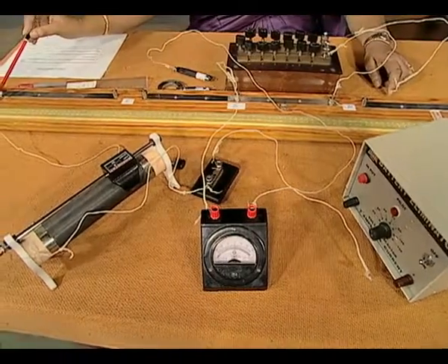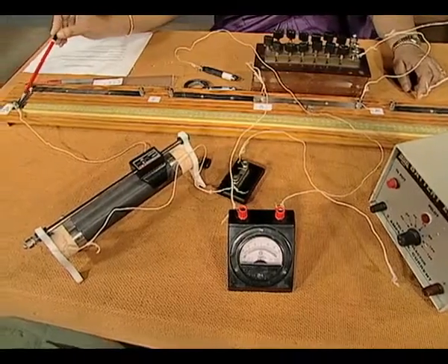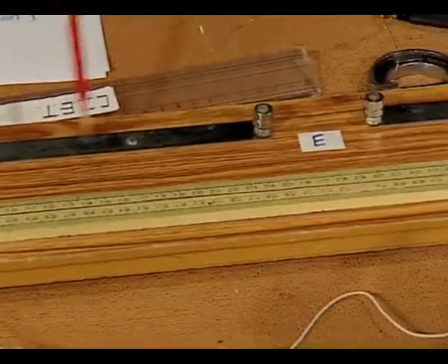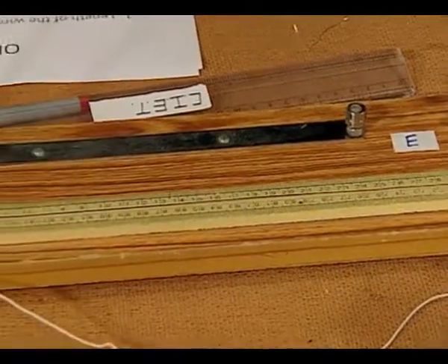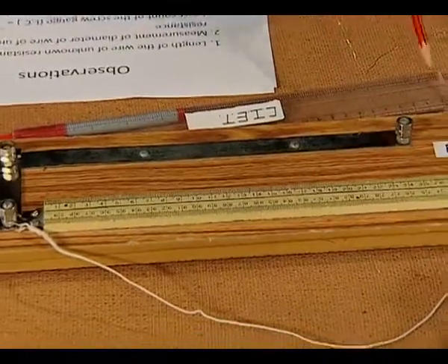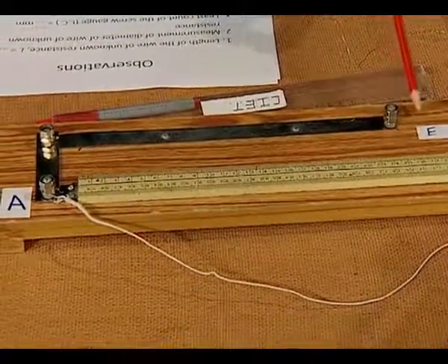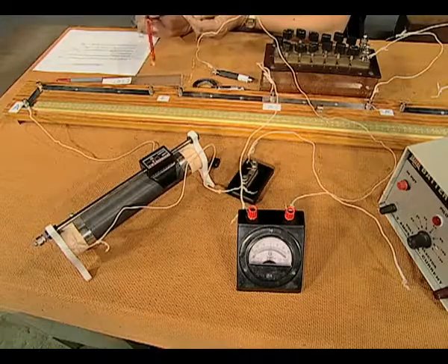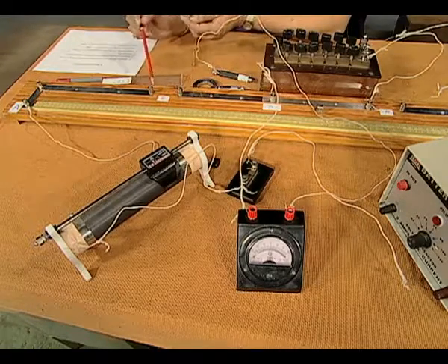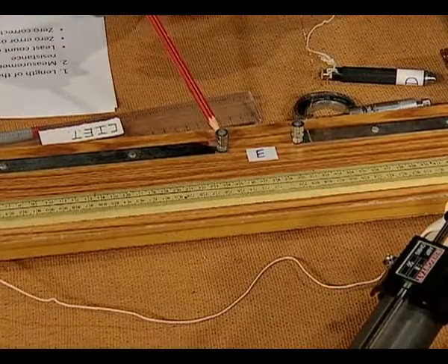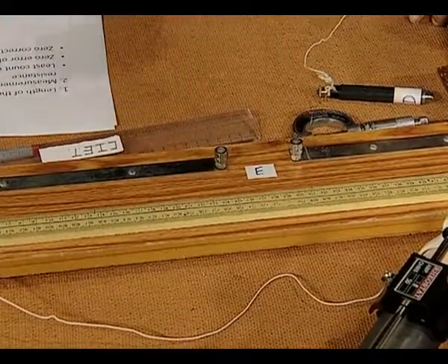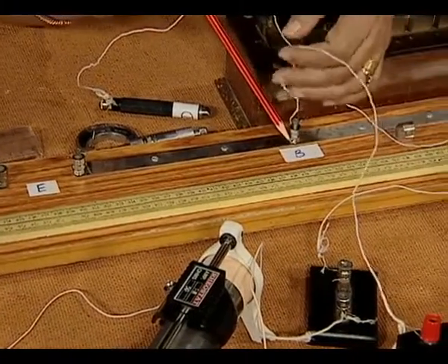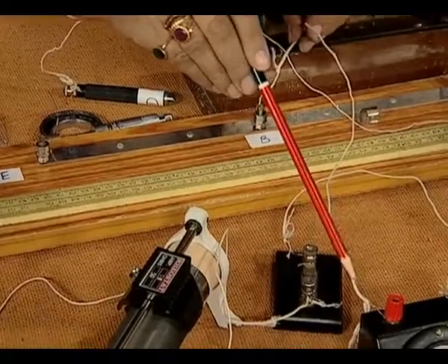The two other connections which are important are through this rectangular metal strip, one portion of it here, the other here, leads to this gap between these two terminals. We are going to connect our resistance wire by finding a suitable length and place it here. The rest of the terminal goes on to point B. From B we have a connection to the galvanometer.